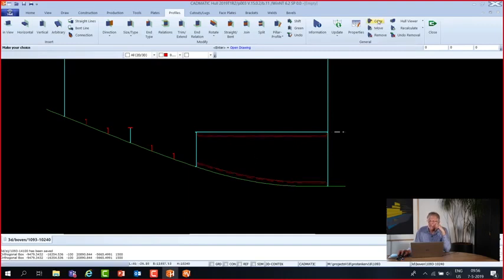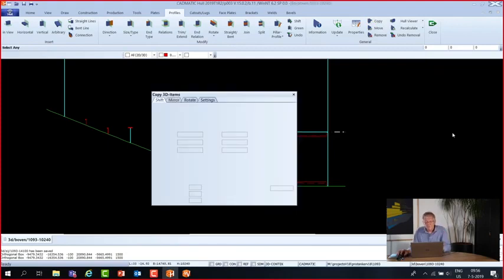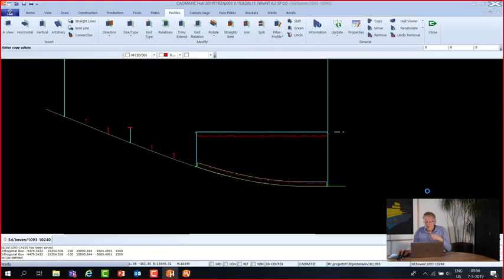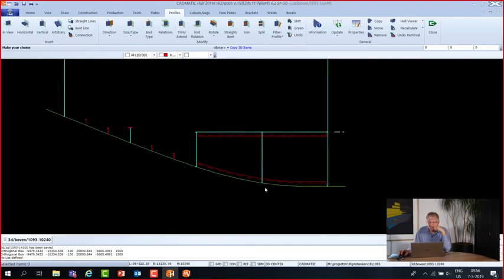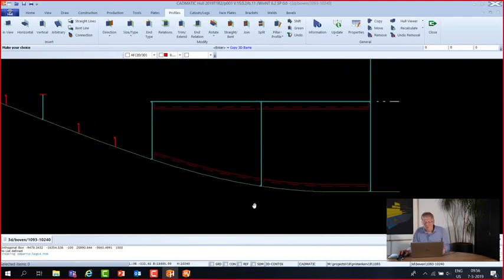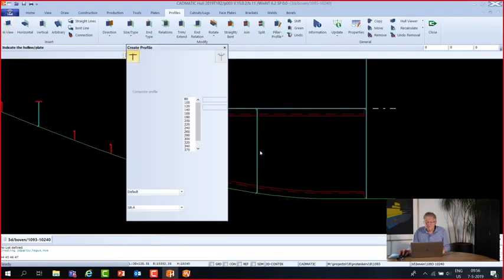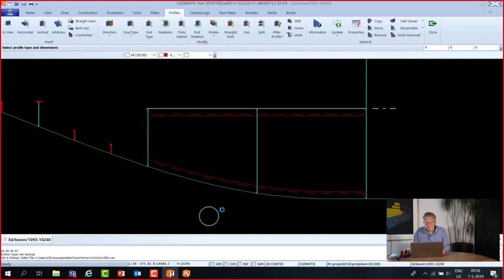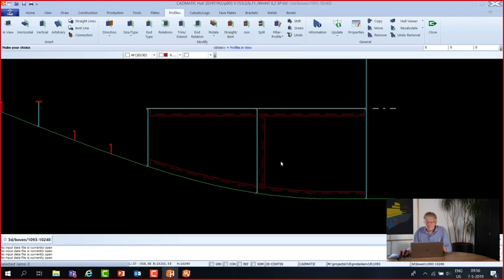So I will copy this bulkhead, again 3 frames forward, to have a bulkhead over here, and you see it's automatically adjusted to the new shape, or to the shape at frame 36. A stiffener here, 167 is okay. From here, automatic end shape until here. And that is okay. Brackets are needed.